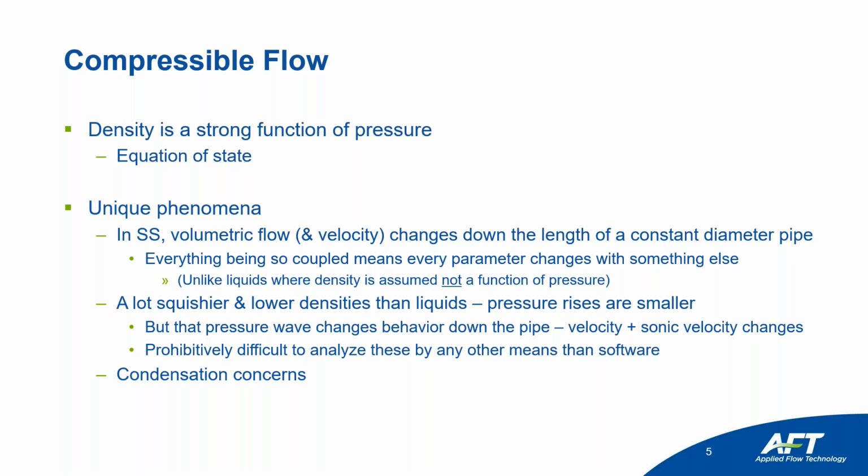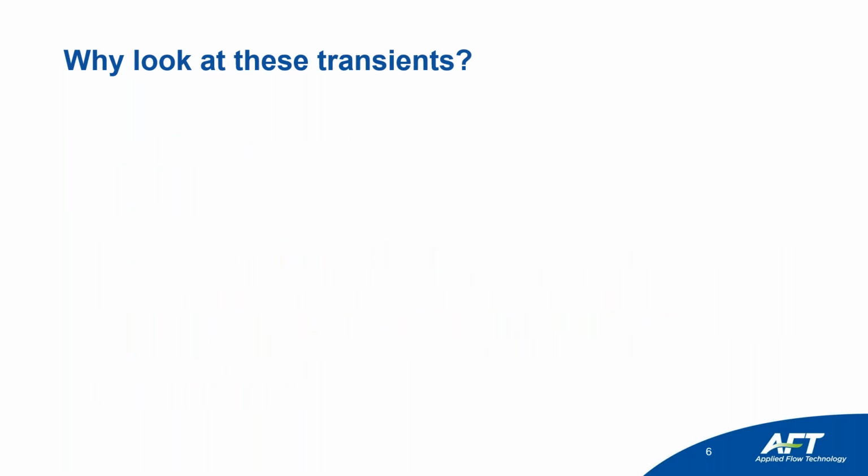There are condensation concerns, especially with steam systems, and then there are sonic choking concerns, also with gas. You don't have that in liquid. So xStream will account for all of these. With condensation specifically, it won't model the slug or the phase change, but it will warn you of condensation, and you can decide for yourself how bad it is, and whether you want to make changes to your system to avoid that.